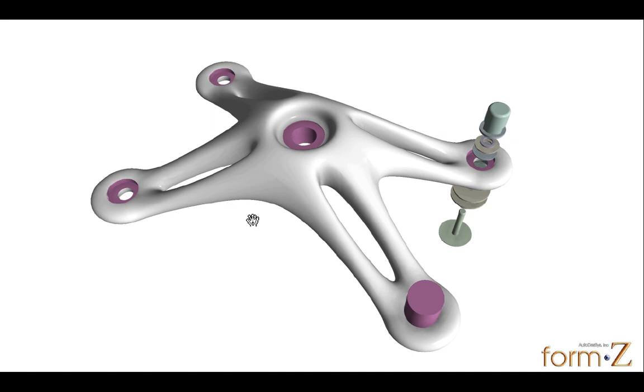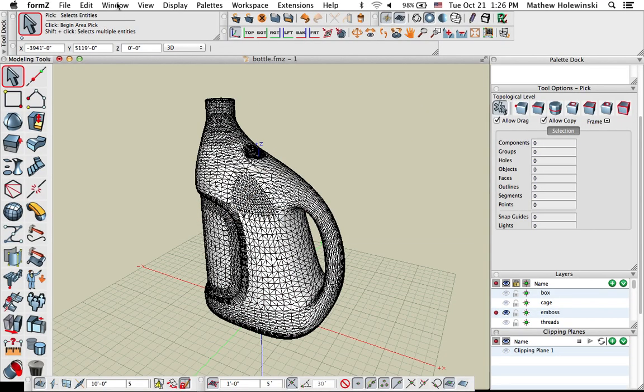What we're going to do is do this little spider clamp, which is a clamping system that's used for glass type curtain walls. And we're going to build this as a subd object, but you can see there's some mechanical type details in here. We got some holes that need to be precisely positioned and drilled, and there's some counterbore holes in there. And how do you get that type of precision out of a subdivision object? Well, let's find out. So what we'll do is we'll recreate that.